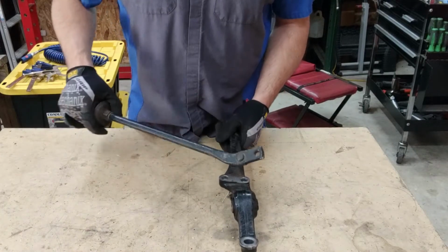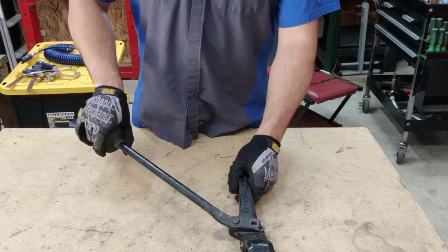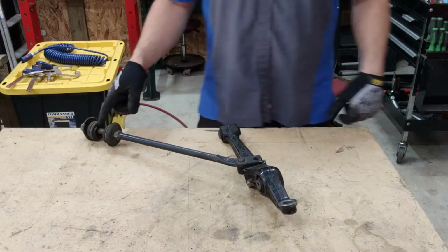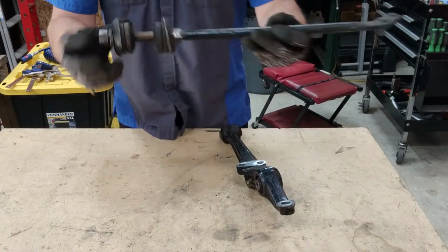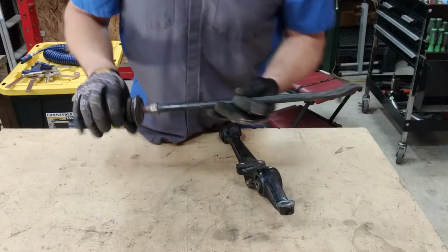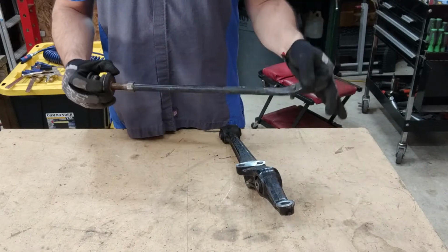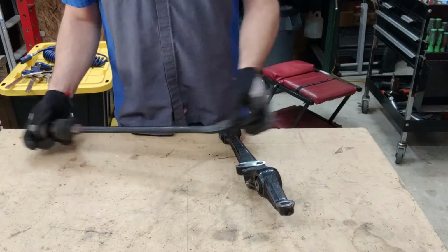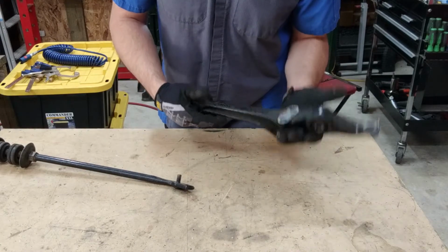So what these usually do is, through mounting holes or mounting studs, connect to the control arm. And then the other end will connect to the chassis. So this component here, through these bushings, will sandwich around a chassis bracket, and it's going to allow some movement up and down through the deflection of the bushings. So that's not going to bind the movement of the control arm as it moves with the suspension.